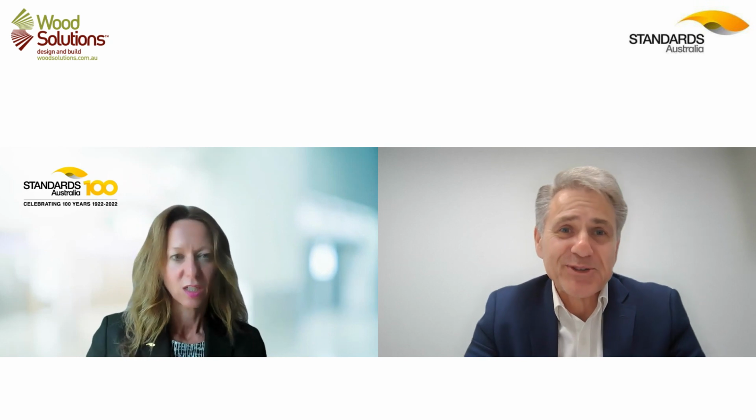Yeah, that's a very interesting question. The grades, I suppose there is an assumption made on the grades. I did a bit of design work many years ago, and I'm now struggling to remember the specifics. But typically, the grades on our decking type products, I'm thinking hardwood, are typically clear. So we assume that it's at the upper level of our stress grades.